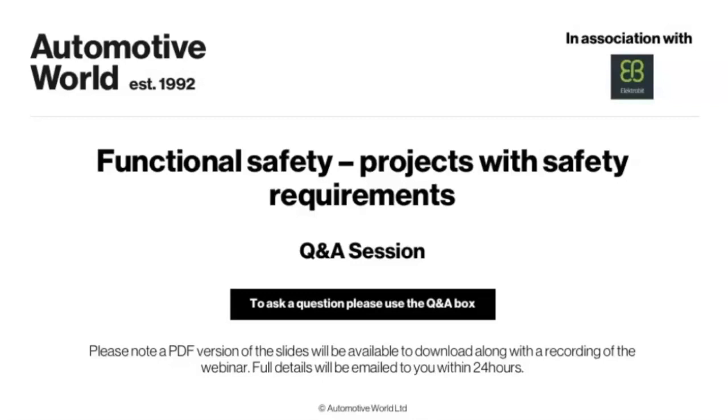Actually, the AutoCore, if that question refers to the ASIL B ready package, you can only rely on up to ASIL B. If you have a system which has an integrity level higher than B, C, or D, and steering would probably be a D, you can rely on the safety product. So it's not the AutoCore, it's the OS, Timey, E2E, and the safety RTE.